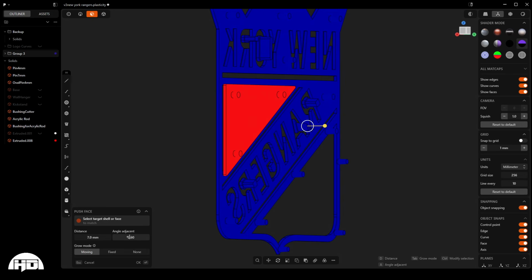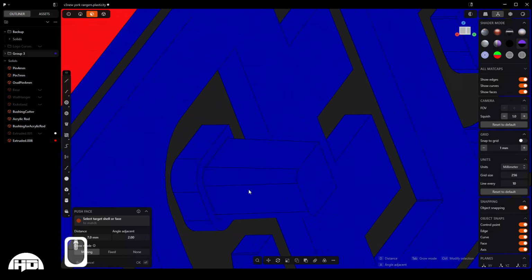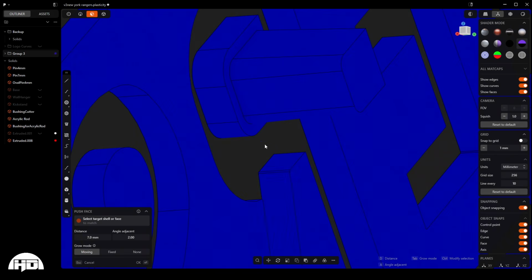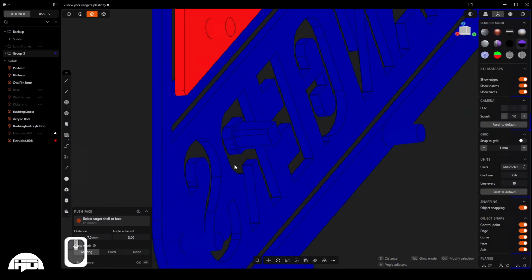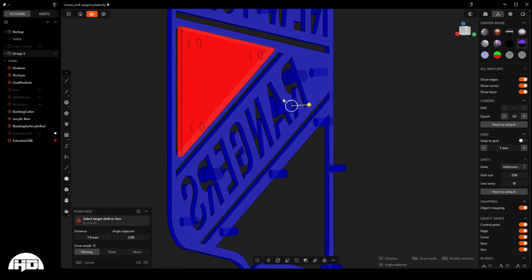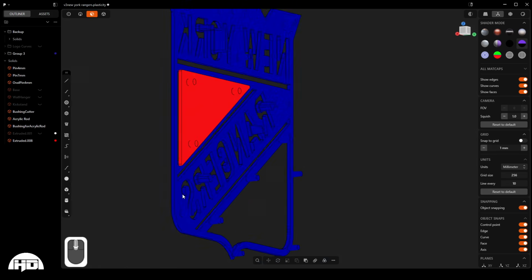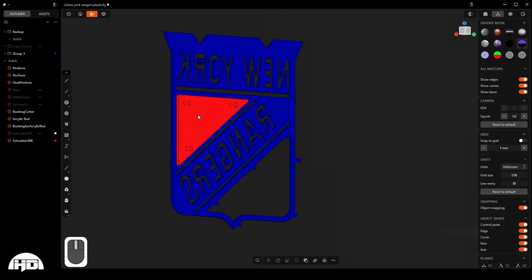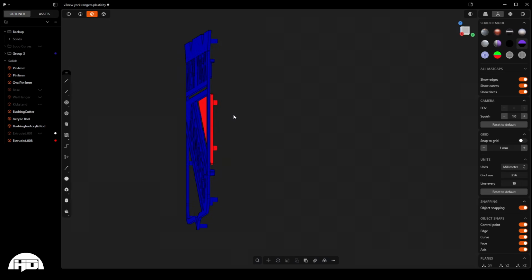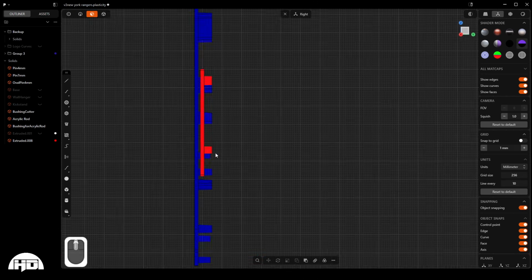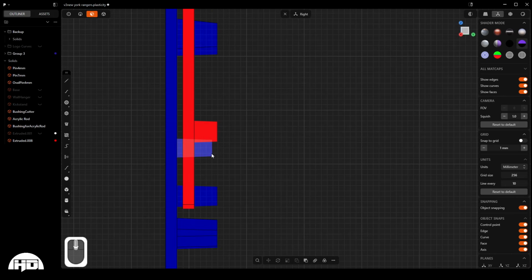But you can see here, we don't have any errors and we got to 2 degrees angle. And you can see it just puts a very, very slight draft angle on those. So that's nice. Right click to commit, and we're done. So that's all the pens. Now let's hit 3. And you can see since we did...